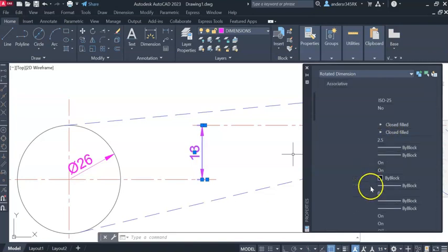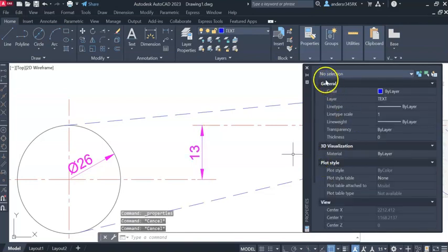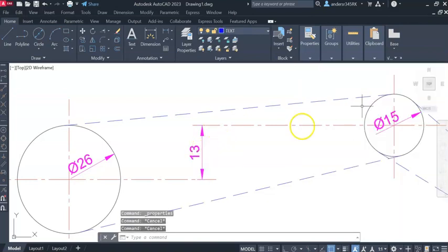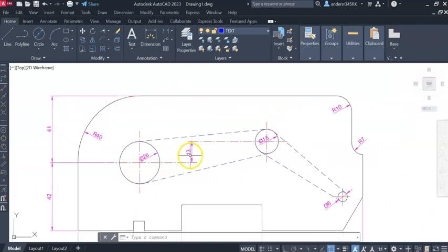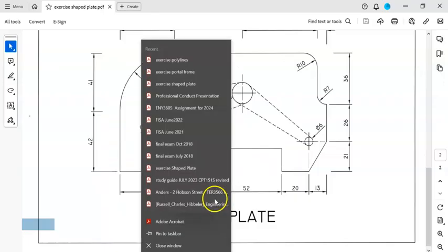It tells you the arrow size, it gives you everything about it. So if you want to inquire, it's called an inquiry command. If you inquire about an object's status or attributes, you click on it, you go to properties, click on the drop down, and you can see how long it is, how short it is, and so on. A little more about it just now. So that's on the right layer there. Okay, so I think I've done most of that over there.